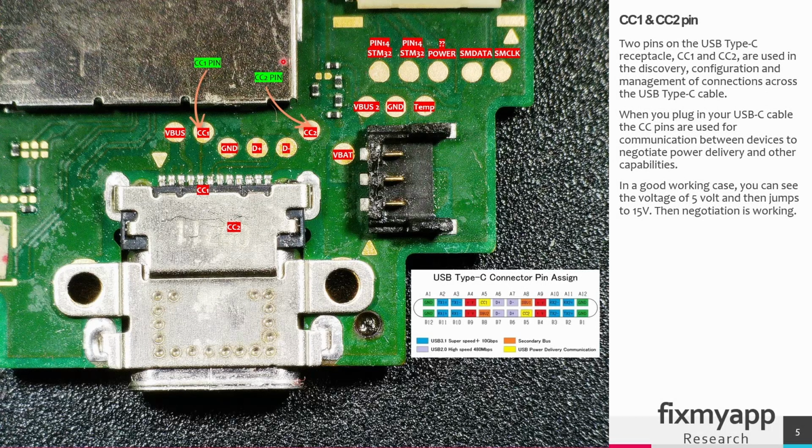Here you can see a Nintendo Switch Lite mainboard. So this is the USB-C port section. This is also called a receptacle. In red, all those pads are test points. I will now focus on the configuration channel pins. The configuration channel pins are located here on the 5th pin. So here's the CC1 pin and the CC2 pin. So the bottom row is located here. The V-bus is on the 4th pin. So here is V-bus present. And the V-bus is also present on the 8th pin.